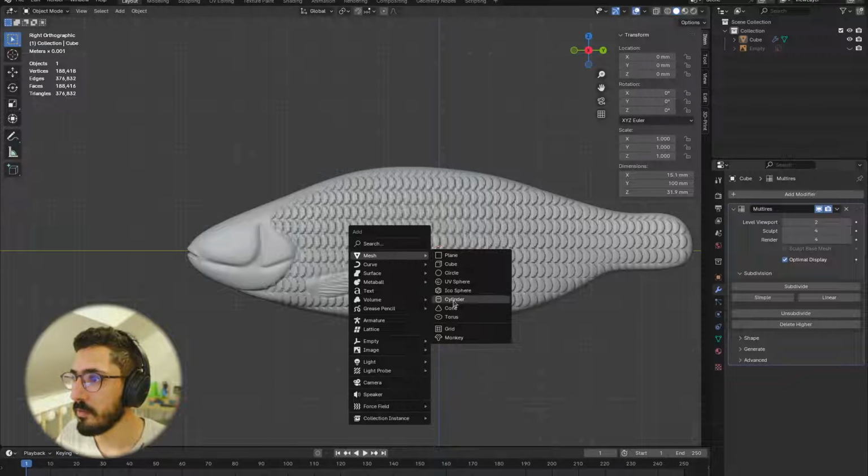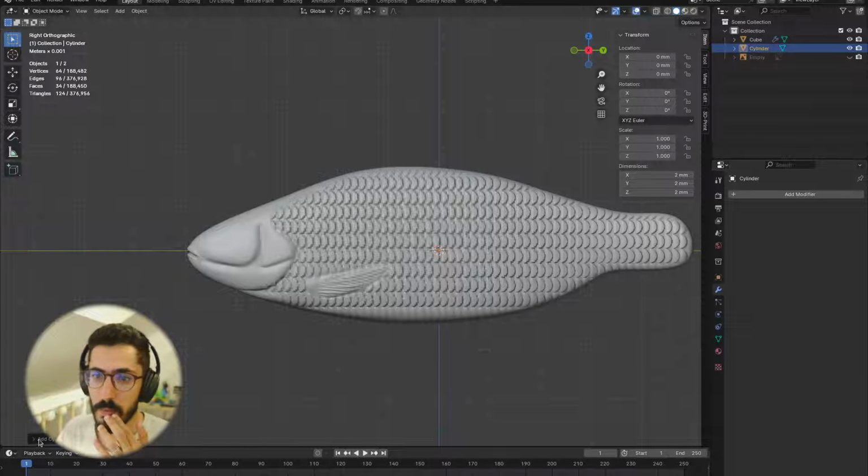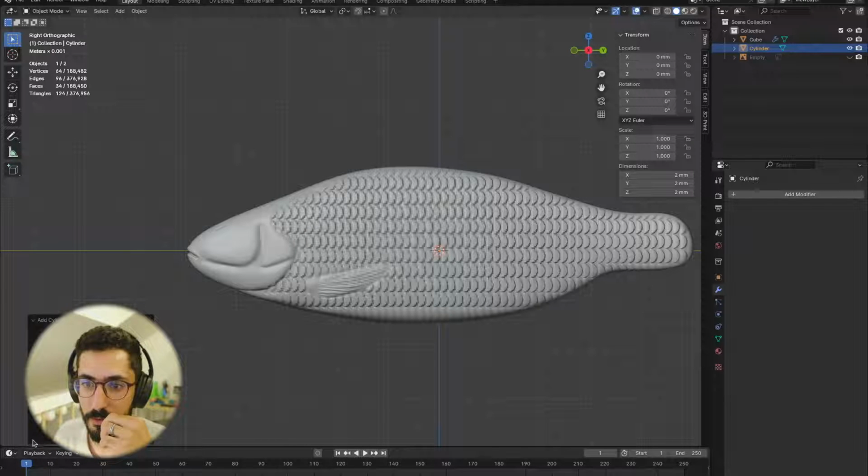So if I add this cylinder now, and we can't see it at the moment because it's small, but if I click here and I change, okay, radius 1 mil, this will make it a 2 mil diameter, that's fine. In terms of depth, this is the length of the cylinder, I want it to be 20 mil, or can even do less.